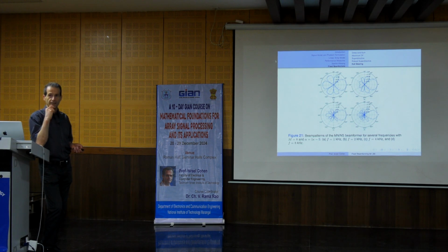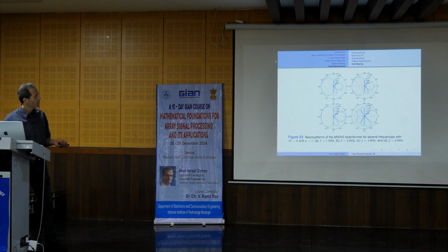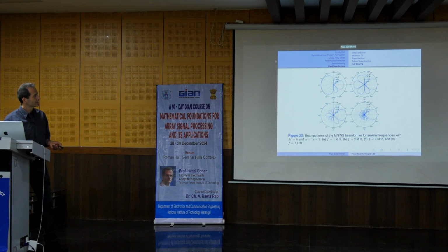Now I increase alpha. If I increase alpha, the white noise gain increases. The directivity factor decreases, which means that the main beam will be wider. Let's increase alpha to 10 to the power of minus 3. So this is before, this is after we increase. You see? The main beam widens because the directivity factor decreases. Let's continue. Let's make it even larger. Make it 1, and you see it's even wider.